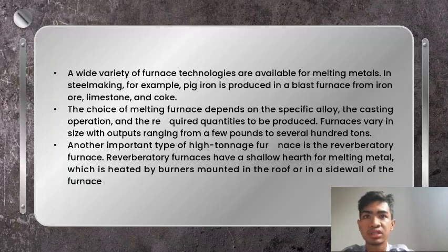For aluminum alloys, the required temperature falls between these extremes. For example, for AlMgSi alloy, typical casting temperatures are in the neighborhood of 680 degrees Celsius. In steelmaking operations and in foundries, the electric arc furnace is commonly used. However, cupola furnaces are used where large tonnages are required for iron making.